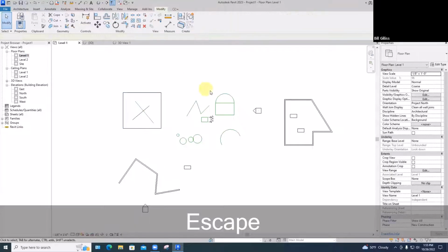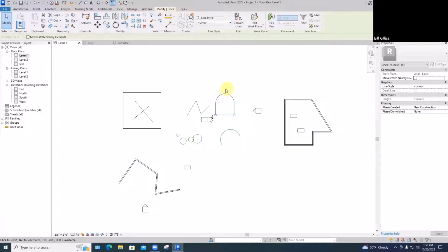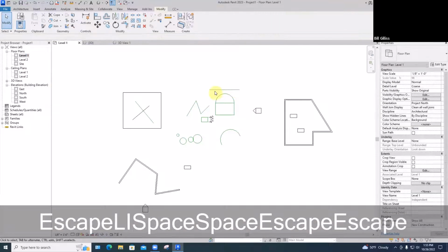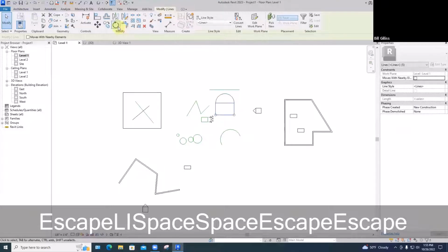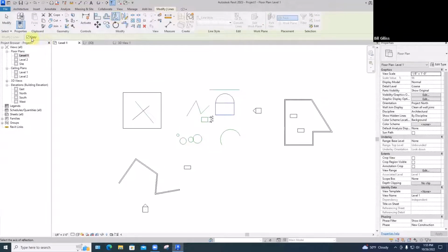One thing to be aware of when we're doing this, let's say I've selected these and I want to mirror them so that there's an upside down version up here. And I'll draw a line first to do that with. So if I window them and pick the mirror tool where the axis of reflection is already there, I have an option over here. This is called the option bar, and it shows up for a lot of the commands. Like if you're drawing polygons, this would say how many sides do you want. In this case, for the mirror command, it asks do you want this up here to be a copy, or do you just want to flip this one up there?